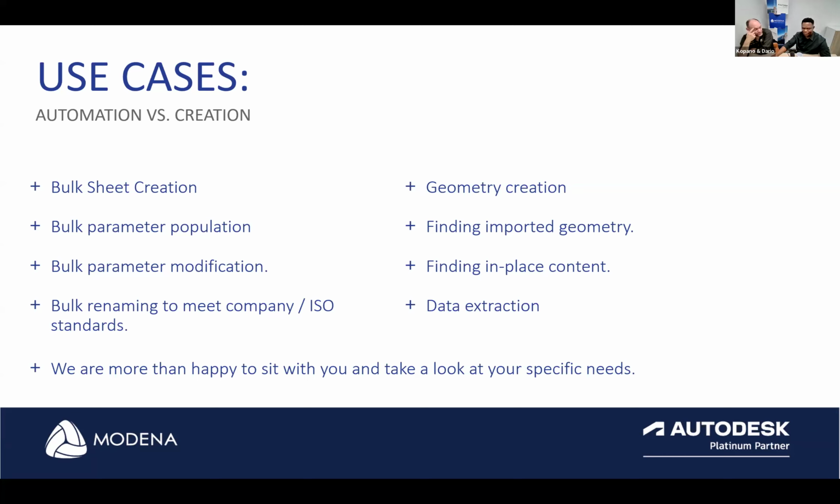Geometry creation from an MEP perspective, I put it in there because it's obviously still valid, but I've seen some structural stuff where you literally push a slider in Dynamo and your entire structure changes. So in terms of iterative design, that's a game changer. Typical housekeeping as well. Imported geometry, imported CADs versus linked CADs. BIM managers generally tend to swallow our tongues when looking for that. In-place families, I'm closing my eyes.